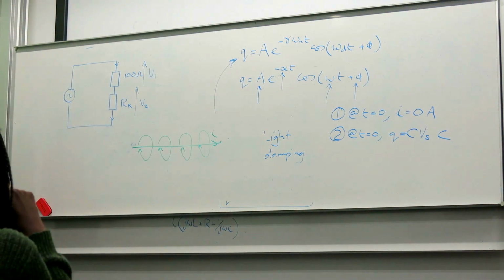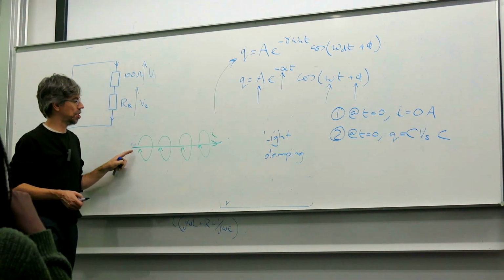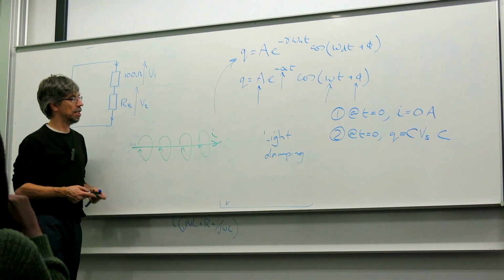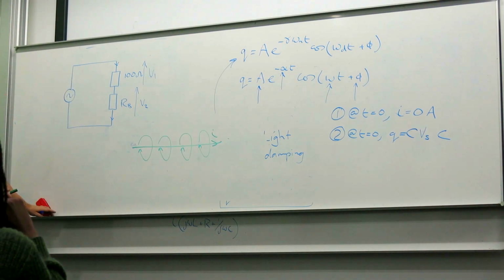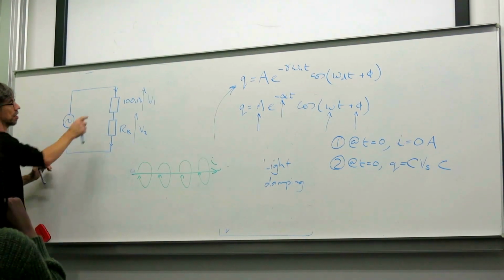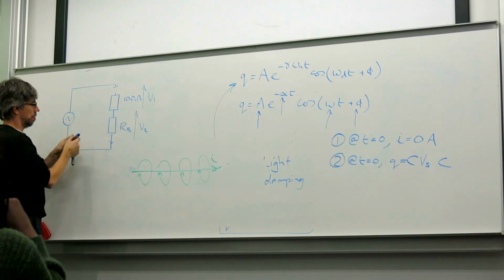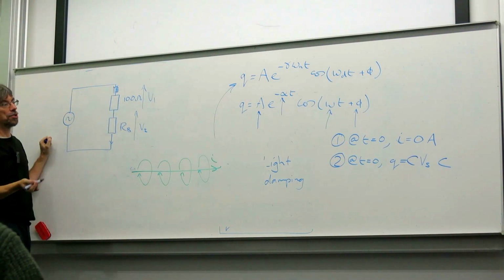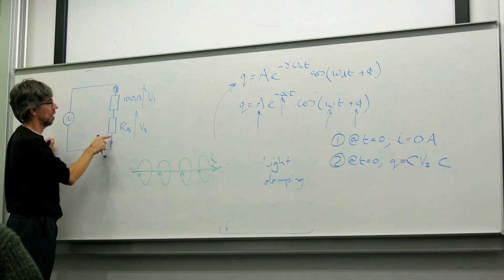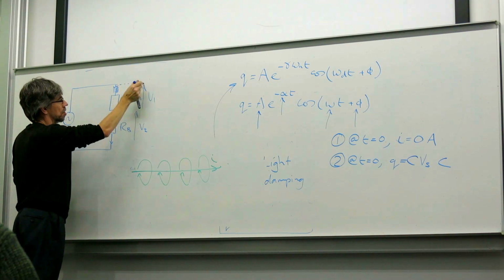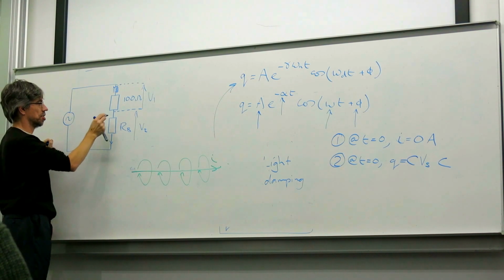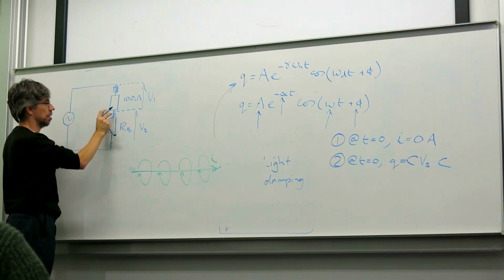So even though we don't want it to be inductive, any wire carrying current does have a little bit of inductance. So if we draw it for the resistor, we've got a little bit of inductance called parasitic inductance. So V1 is measured across the resistor plus its parasitic inductance, and the same for the resistor box.